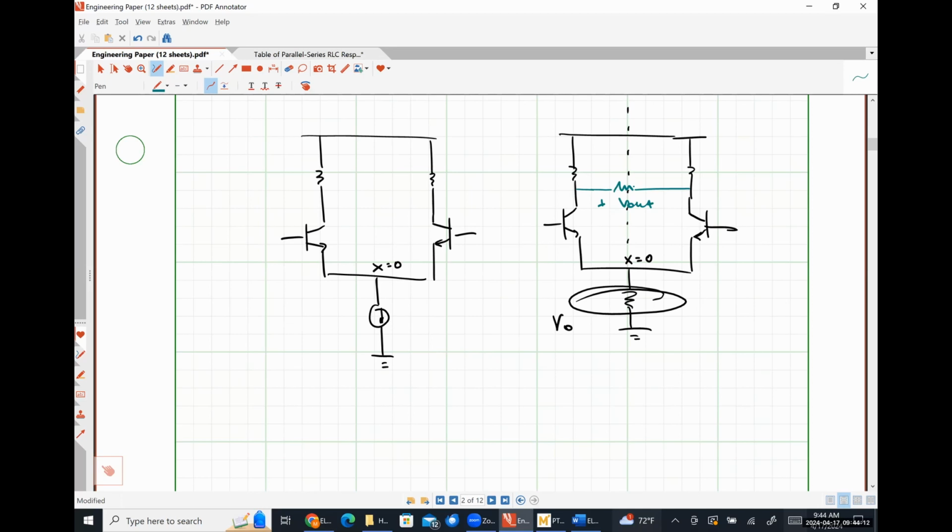On the homework, the last problem where we had two cascodes, we were allowed to assume they were matching. Absolutely, yes. For that particular problem, what I was expecting you to do was say the circuit is symmetrical, so we're going to use the half circuit method, draw the half circuit, say, oh, I'll be damned, this looks like a cascode amplifier loaded with a cascode current source, which looks like this and has this relationship, and call it a day.